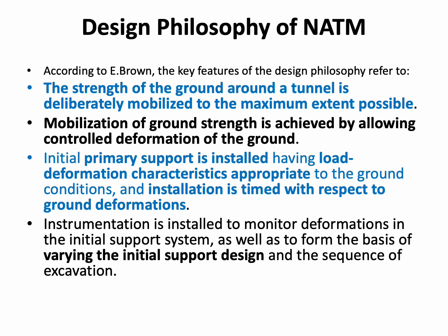The design philosophy of NATM, according to Brown: the key features of the design philosophy refer to the strength of the ground around a tunnel being deliberately mobilized to the maximum extent possible. Mobilization of ground strength is achieved by allowing controlled deformation of the ground. Initial primary support is installed having load deformation characteristics appropriate to the ground conditions, and the installation is timed with respect to ground deformations.